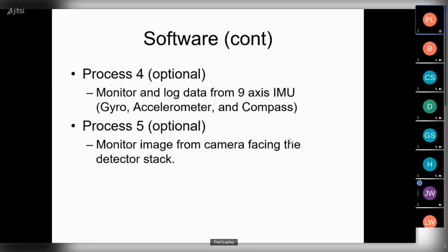So they have about your resolution, but they're usually longer. They have maybe 36 emitter-detector pairs that they scan, and because they're synchronized, they can narrow the bandwidth, and they don't have to have the photodiode wide open all the time.